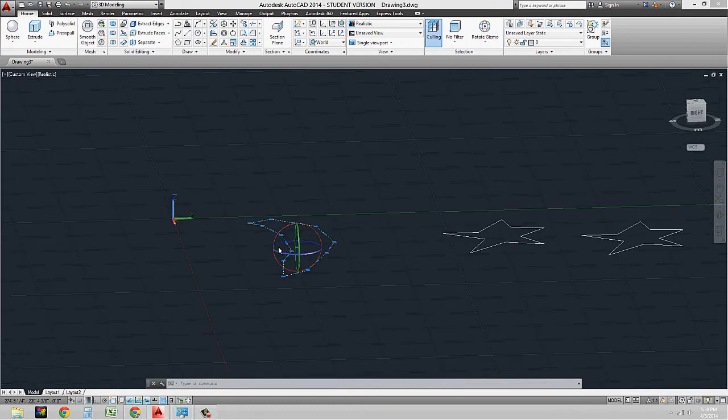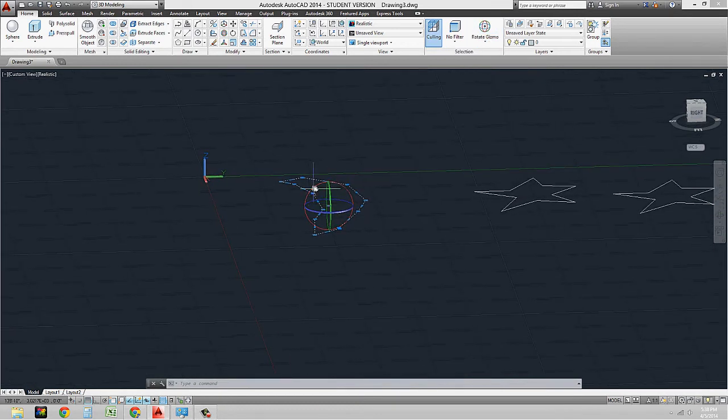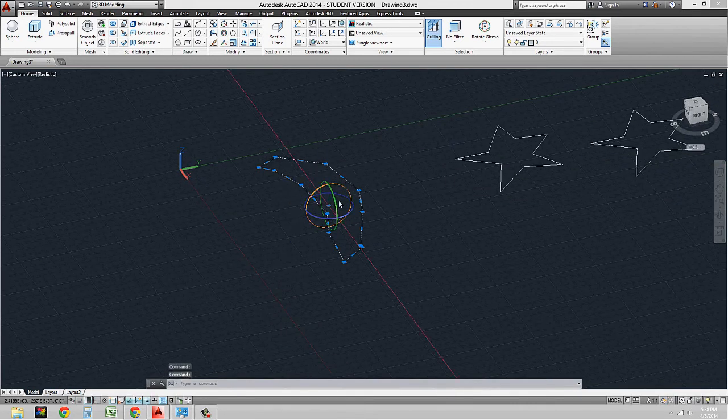Okay, so what I'm going to do is use the rotate tool, and the way that we use these tools is I need to mouse over an axis, and you see when I do, it highlights yellow, and you'll see that it has a color that's associated with the axis that is selected. So for example, if I want to rotate this so that it's standing up, I'm going to use this red axis, and in order to do that, I'm going to click on it.